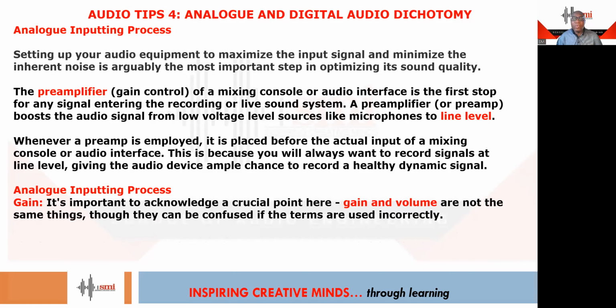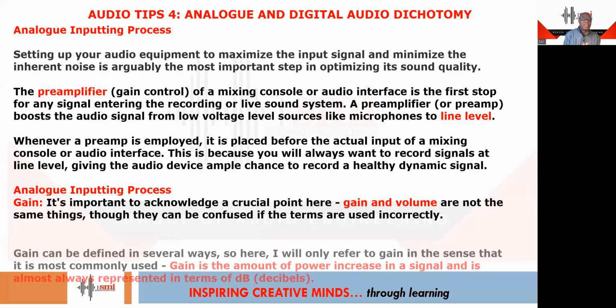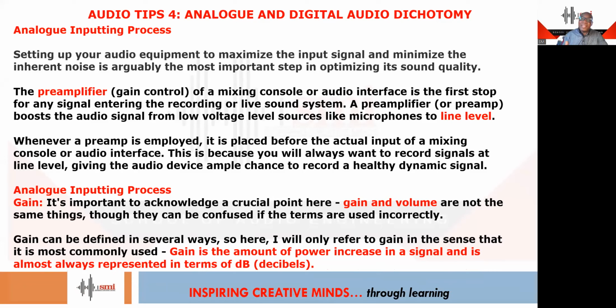It's important to identify the crucial point here. Gain and volume are not the same thing, though they can be confused if the terms are used incorrectly. Let me just explain gain. Gain can be defined in several ways. So here, I will only refer to gain in the sense that it is commonly used. Gain is the amount of power increase in a signal and is almost always represented in terms of decibel.